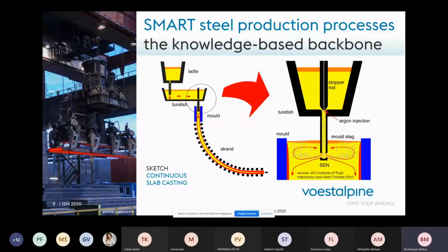the ladle via the so-called tundish in the mold of a continuous casting machine. The liquid steel starts solidifying in an oscillating water-cooled mold. The solidifying shell is cooled with water from the outside, and the completely solidified strand is continuously withdrawn from the caster.